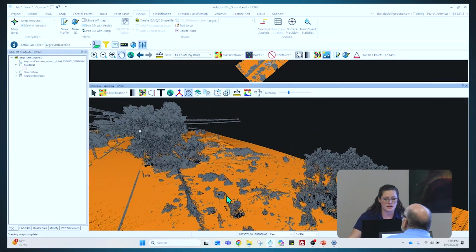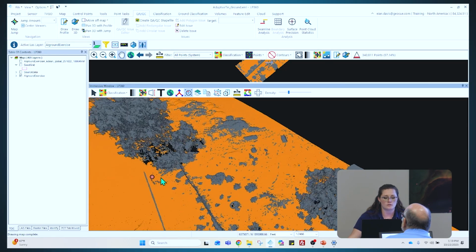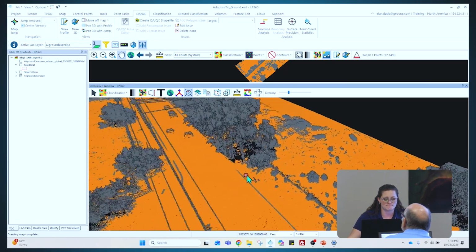That is something to keep in mind when you are flying your own missions and collecting your own UAV data: if you do have anywhere with dense vegetation, it is recommended to fly in a cross-hatch pattern to allow you improved capability of canopy penetration.